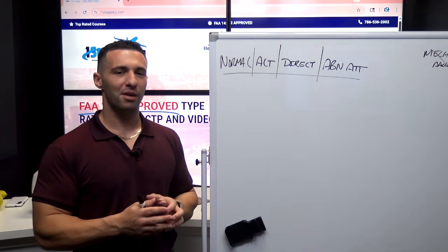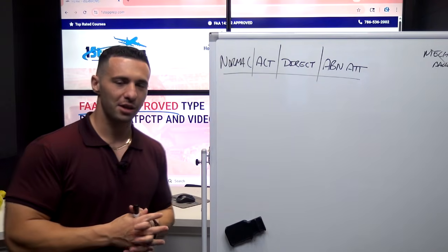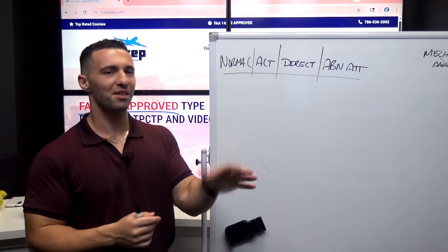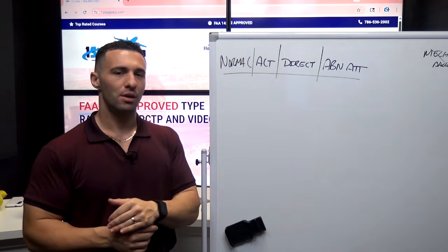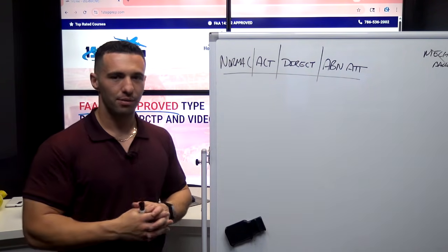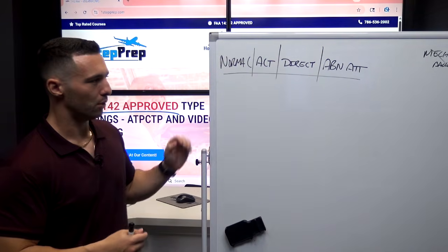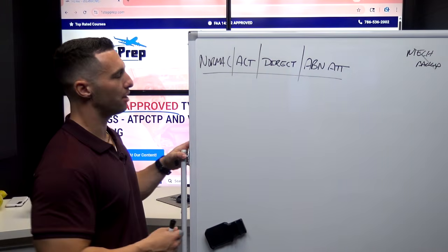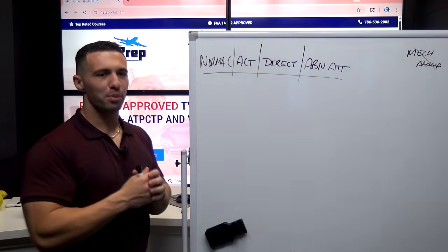I think the better response, if ever asked in a training or checking scenario, what does amber X's mean? It means I'm not in normal law. I am not in normal law. I could be in any of these other different variations of a law or lack of a law altogether with mechanical backup. In alternate law, as far as protections,